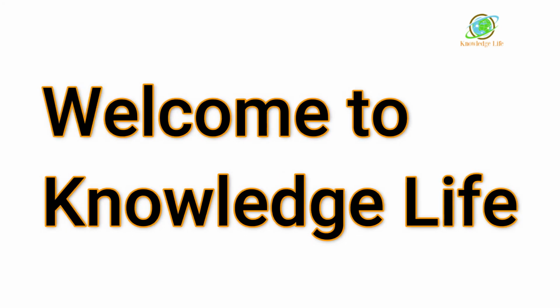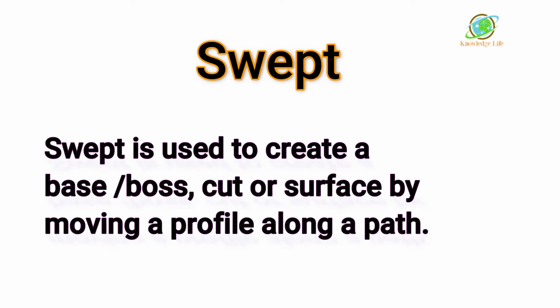Today in this video we are going to talk about one of the most powerful commands called sweep. Sweep is used to create a boss base, cut or surface by moving a profile or section along a path, and you can control the shape by using the guide curve, which is an optional feature. A sweep might be simple as well as complex.